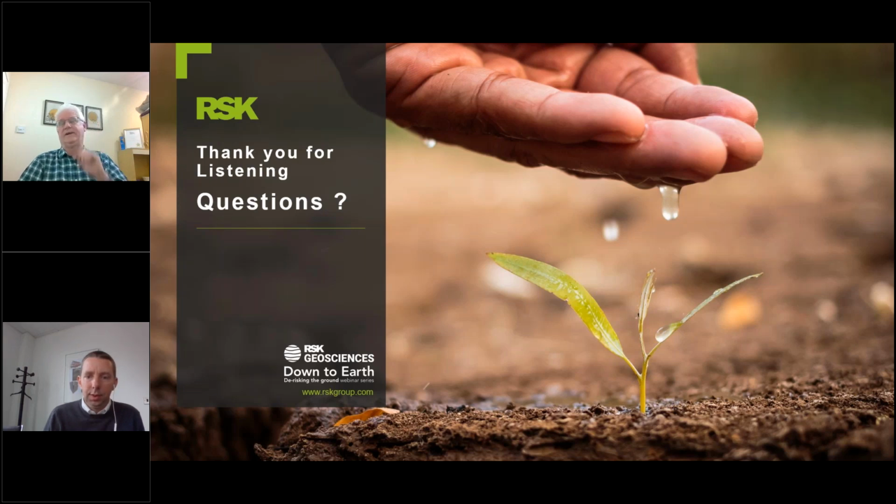That's a brilliant question as well. To be honest, there's a lag in the time it takes for the moisture change to take place as well. And because we're dealing here with a soil of a very low permeability, these are sustained changes over a long period of time. So they're not like a short-lived change. You aren't going to get one sudden wet summer make the clay suddenly wet or suddenly dry, if you get me. So it's going to take a sustained period of time for that significant depth to reach the stage that it would be in its worst case. I'm not sure if that explains it well, but there's a lag in that time.